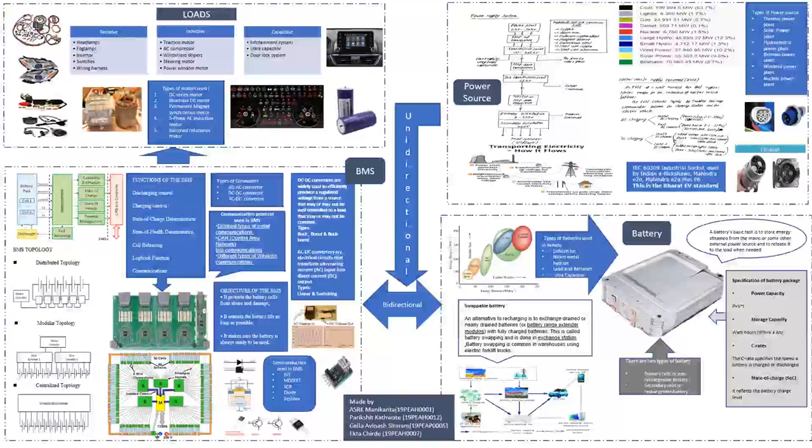Again, there is also specific energy. Specific energy or energy density, both are the same, which gives the battery capacity by weight, like watt-hour per kg. Again, from the specific energy, we can find out the specific power, which indicates the loading capability of that battery. Also, batteries for power tools are made with high specific power and come with reduced specific energy.